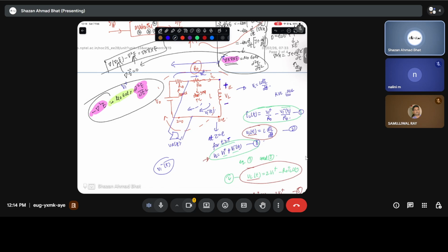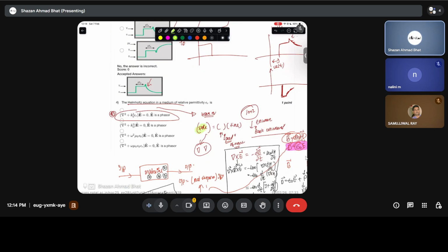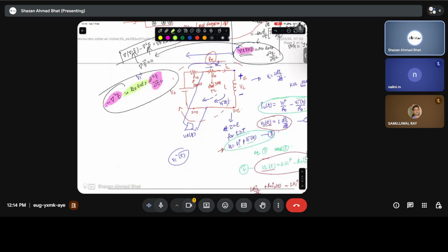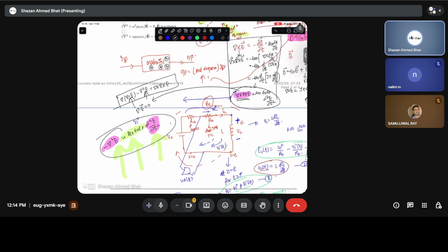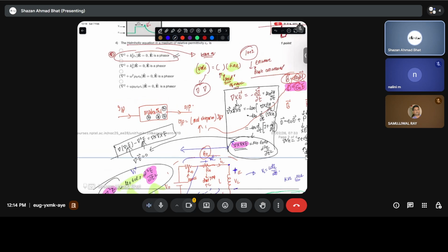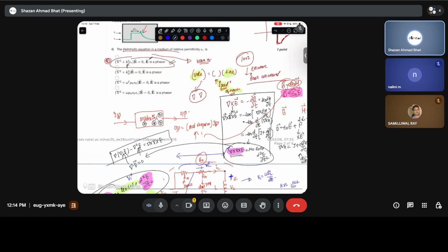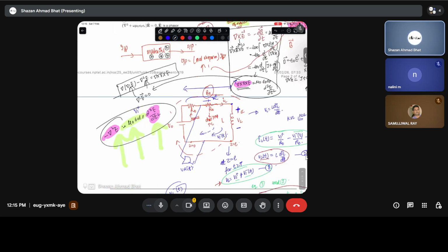So it's almost like a wave equation. Just like I told you in simplistic terms, there's a space term, there's a time term, and then there is a speed of the wave. That is basically what this equation is representing. If you simplify it, bring the terms here and there, you arrive at this particular equation, which is called the Helmholtz equation, where this k naught is the wave vector, and you know that E naught can be written in terms of a phasor quantity, with a certain magnitude and e to the power j theta, a complex term.